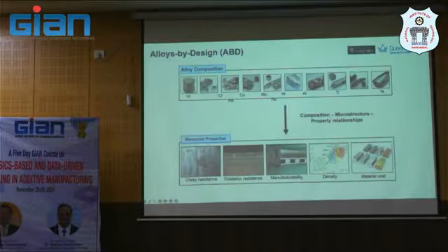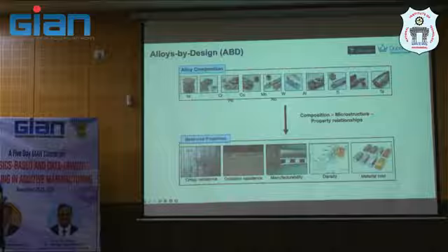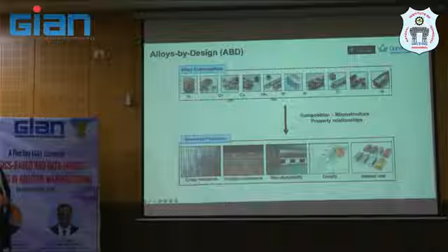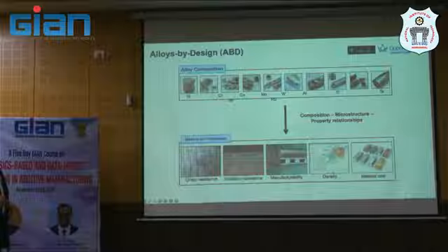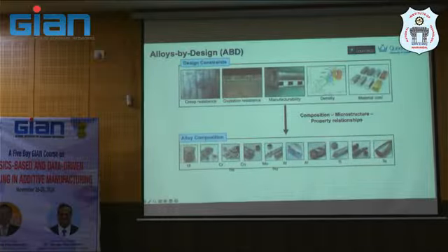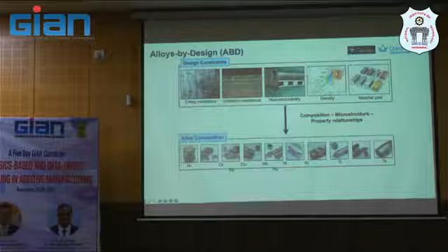And this is the alloy composition here we consider with the major properties that we can have: creep resistance, oxidation resistance, manufacturability, density, and then material cost, because cost is a big factor for the new design, right? You need to take that into account. And you have the composition-material property relation. But the alloy by design framework is a bit different. So we want to understand the design constraints here backward, and then we want to work out what composition gives rise to these properties.